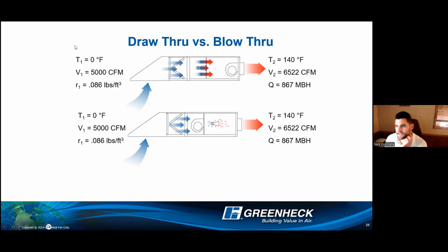Our design is creating an even flow, even pressure, non-turbulated air. You're bringing in what we would call clean, non-turbulated air across the burner. Why? When you're doing a blow through, you are pushing air over that burner. It's uneven, it's whipping, it's mixed. You may have pressure fluctuate. That can cause a unit to not work properly. It's definitely not going to be as reliable as a draw through design.